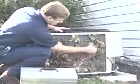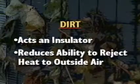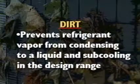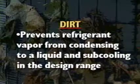An examination of the condensing unit outside reveals that the coils are clogged with grass and dirt. Dirt acts as an insulator and reduces the ability of the condenser to reject heat to the outside air. This prevents the refrigerant vapor from condensing to a liquid and subcooling in the design range. Clearly, the dirty condenser is at least part of the problem and should be cleaned thoroughly.